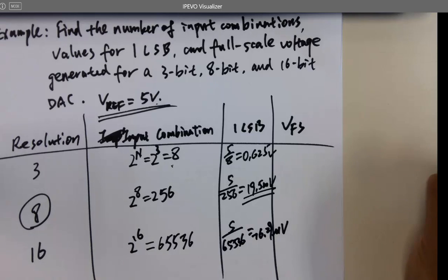Barely. The oscilloscopes we have here go to 20 per grid. 1 millivolt you can still display, but it's getting really noisy. So just let you know that 1 millivolt is pretty much one of the lowest voltages you can see in decent quality on the oscilloscope.